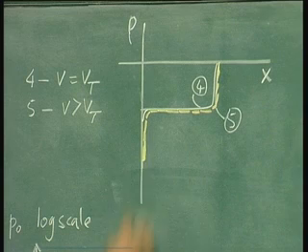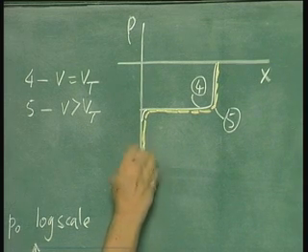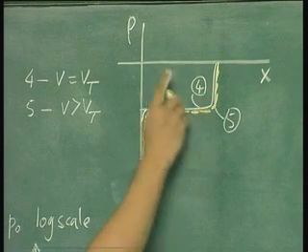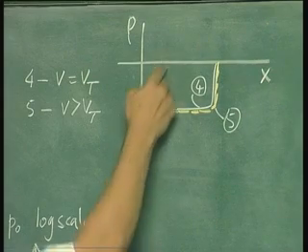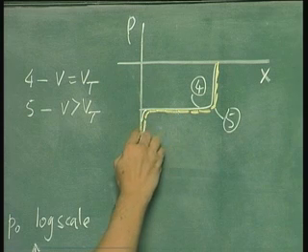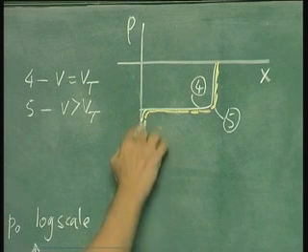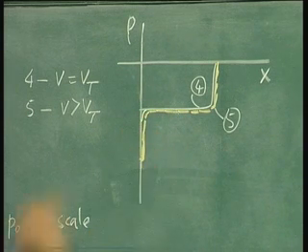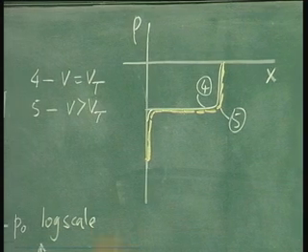So this is the charge that we are talking about. Now you no more have to increase this area under this rectangle to get the charge. Extra charge beyond threshold comes from increase in this negative charge because of electrons.